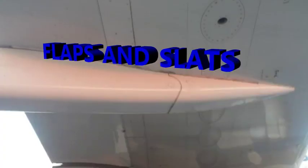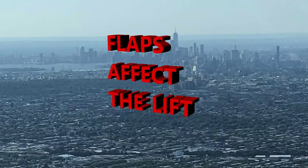Your flaps and slats are going to be primarily your secondary flight controls, and flaps, for example, are going to be affecting the lift. It's sort of a high lift device, and its job is to increase the lift of the wing at a certain airspeed.